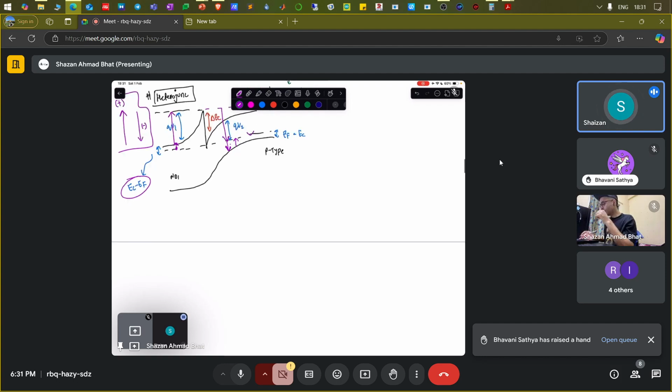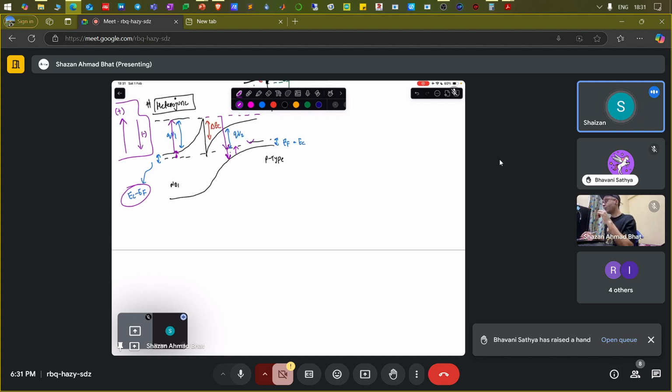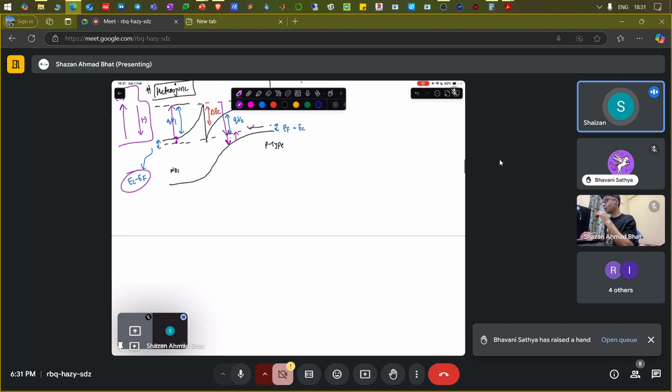Okay, now once we move in a particular loop fashion, we can sum up all the voltage in a path. Let's consider the first path. Let me just draw a schematic of this. This is the first path, which is from this Fermi level to the conduction band on the left hand side. Then you went up again, which is basically QV1. Then you move to the other side. Then you went down as the delta EC, the conduction band offset. Then you went again overall down, which is equal to the band gap on the other side.